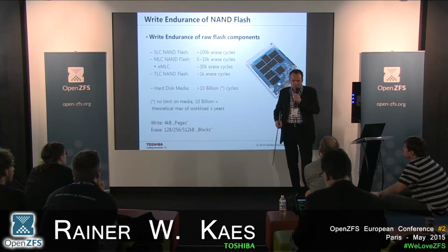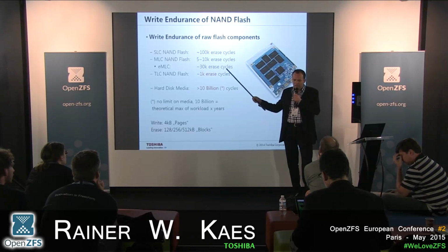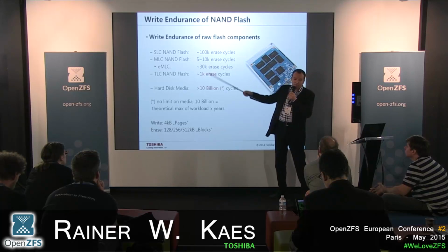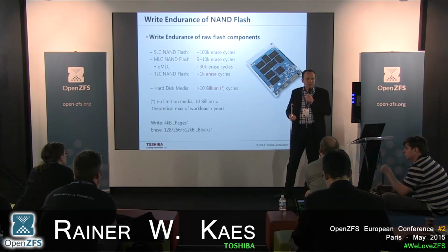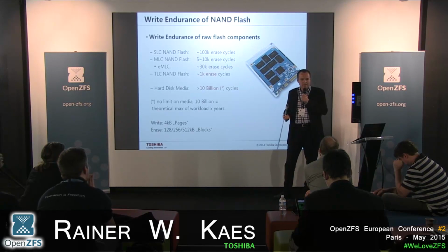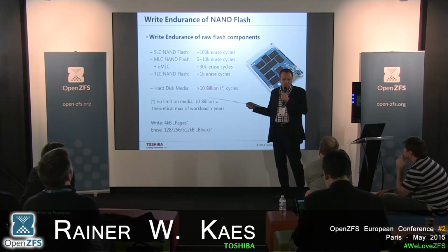We don't need reliability tests to predict this. We can write to our flash components in testing to determine these values quite fast, within a few hours. So we can easily measure how many write cycles they will accept. And if they go over that number of write cycles, they are just dead.